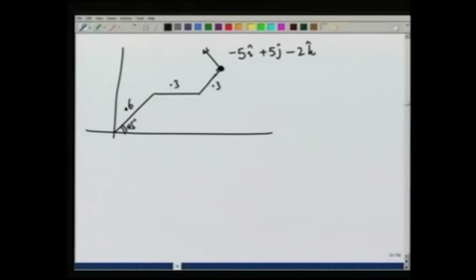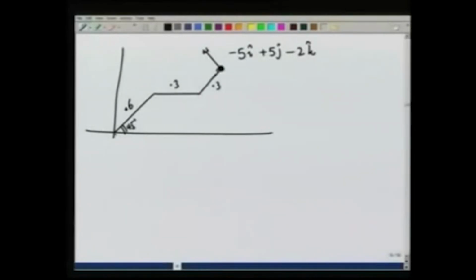The torque of the force is going to be R cross F. Equivalently, I can think of an equal and opposite force being applied here and force equal to the original force being applied at the bottom. I have done nothing but added a zero force onto the system. Now, this minus F and the original force therefore create a couple here, which is given by tau, and the force is the original force here. Let us therefore calculate this couple.